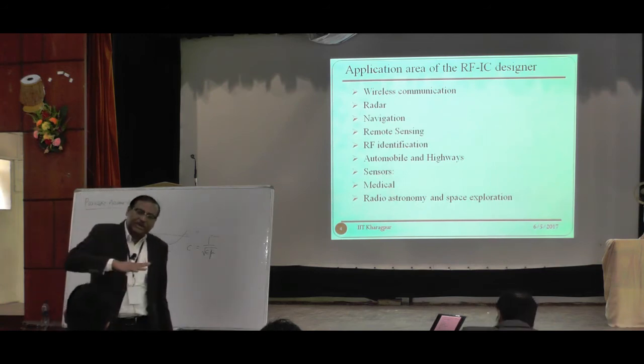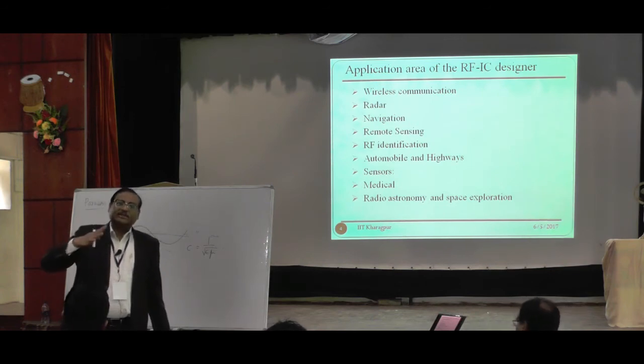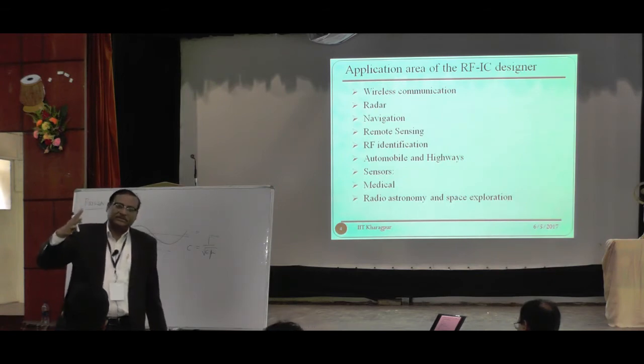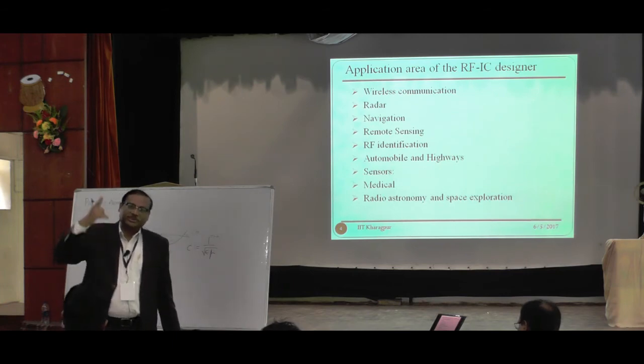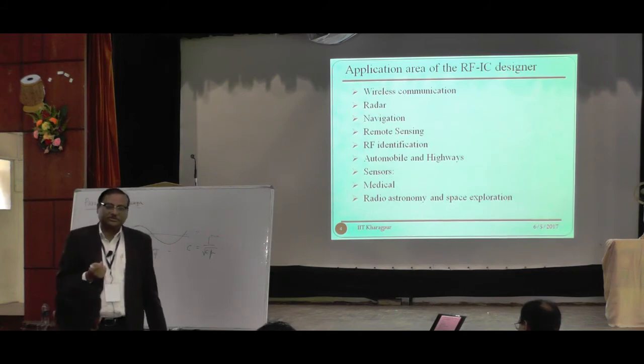Then, regarding the lumped parameter model and the distributed parameter model, when the component size is 1/10 of this wavelength, the lumped parameter model starts to fail. So 3 millimeters, 0.3 millimeter.